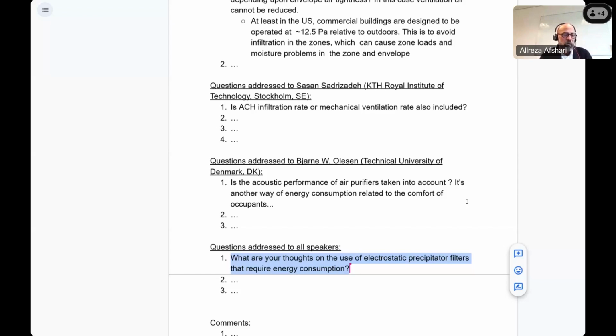We have done this study, and we used this kind of air cleaner in a room without ventilation and waited 24 hours to see what happened. We used limonene and also ozone together in the room. The result was that a lot of ultrafine particles accumulated in the room. So it is very important to be careful that the device you use to clean the air doesn't generate even a small amount of ozone in the room. Yes, I hope that answers the question.